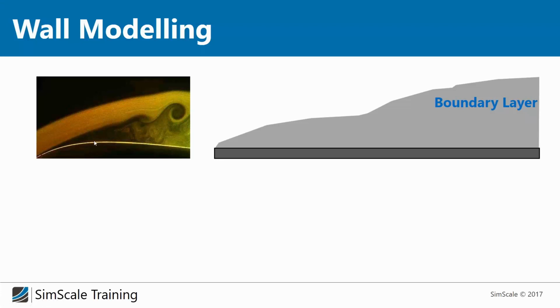In case you ever worked on a fluid dynamics project, I'm quite sure you heard about the so-called boundary layer. The essence of the boundary layer theory is that if we have a fluid flow which is streaming around, let's say, a solid body, we have interaction between the fluid flow, or let's say the air, and the wall. And if you take a look at the flow near the wall, you will notice that this flow has a different structure compared to the outer flow.